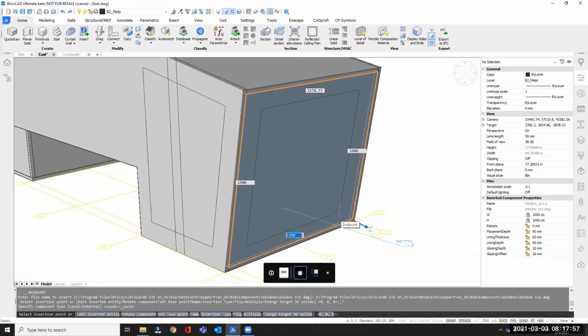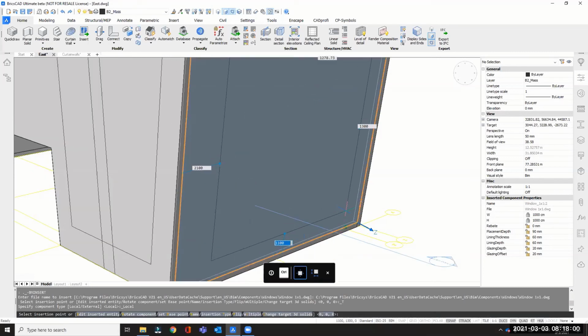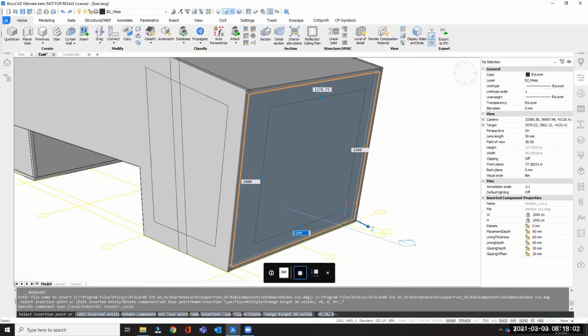So you see that we have our dynamic dimensions being highlighted in blue. To input the information, I might just want to type in the numbers. So for example, on the left side, I will click on tab. Remember that you just click on tab so you can go into each of these dimensions. And on this left side, we might want to put in 1007. So just click tab, and then it will instantly be locked and placed 1007 millimeters away from the leftmost side of our wall.